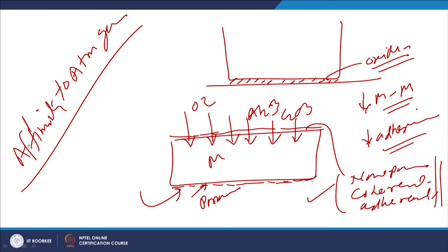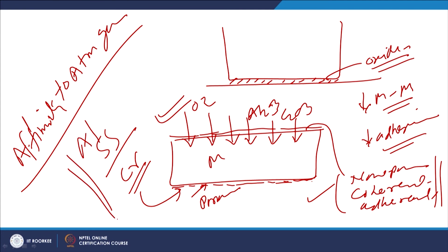So, in this case the corrosion resistance will be less, and the rate at which material is lost from the functional surfaces will be more as compared to the other case where coherent, stable, non-porous and adherent oxides are formed on the surface, like in stainless steel or in chromium and aluminum components.